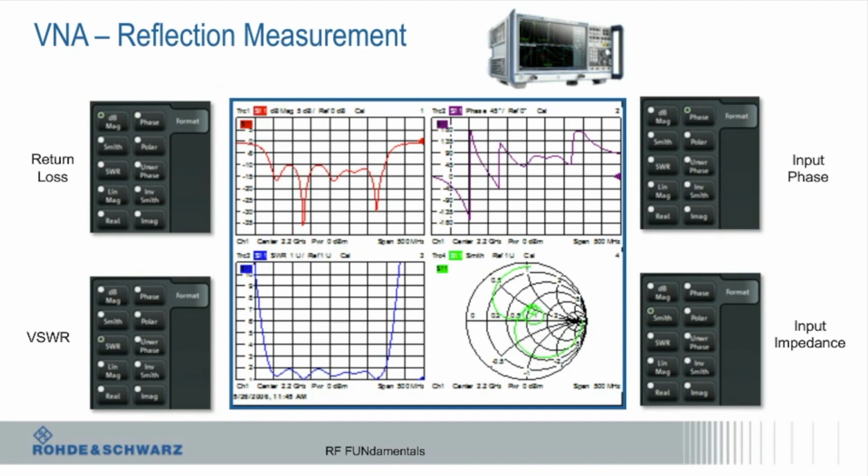That's where you would care: if at my input, my thing was perfectly 180 degrees out of phase, it would cancel out my input, right? If it was perfectly in phase, it would make my signal bigger, but probably distort it. Okay? I might want to look at input impedance on the Smith chart. I'm going to talk a little bit about the Smith chart later, but not in great detail. Unfortunately, people don't really use it as much anymore. VSWR, VSWR. Okay.